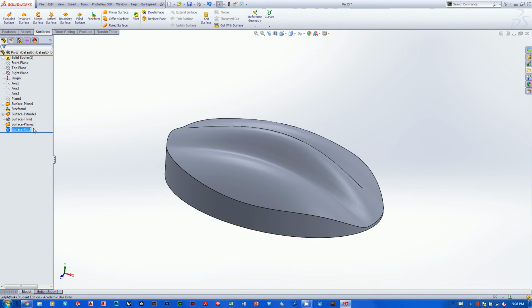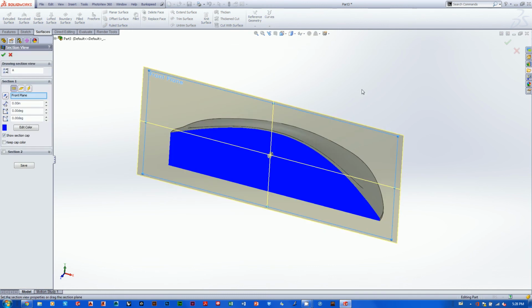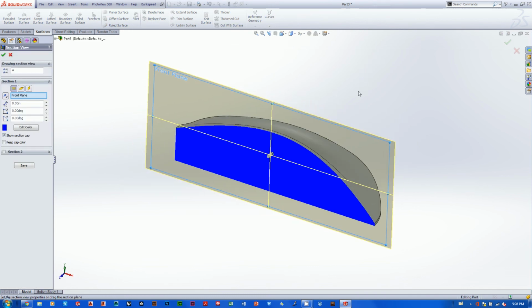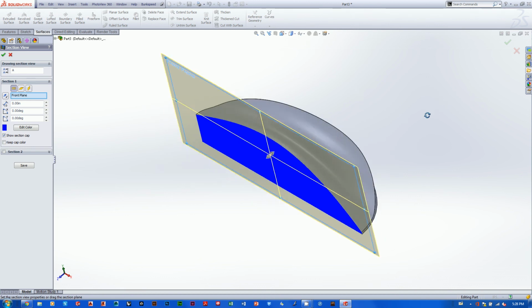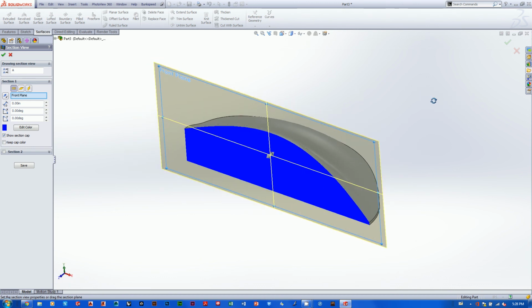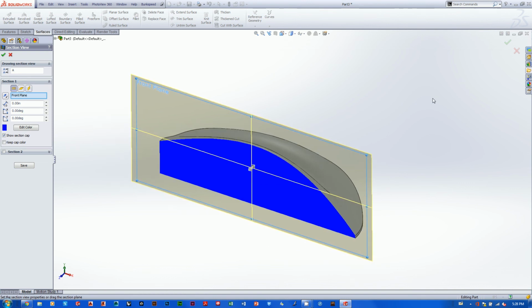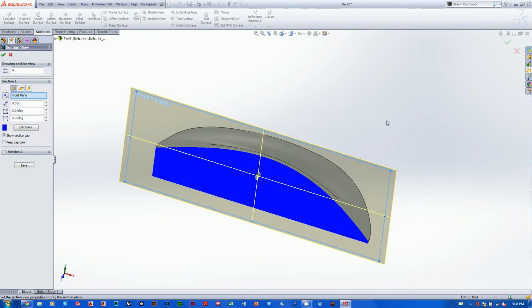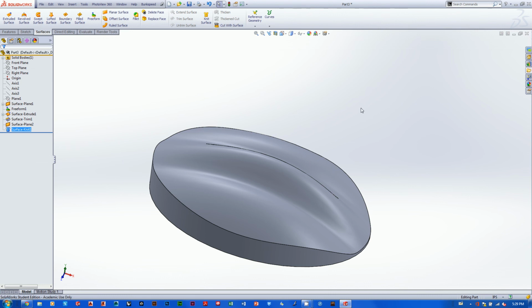Okay, Surface Knit 1 is there. All these surfaces are knitted together. All right, let's check it again. Now what we have is we've created an actual solid from those surfaces. So voila, this is what they call creating a watertight model, knitting your surfaces together. In Alias, they call it stitching a model together. And in Rhino, they call it something else, which you'll find out about in the second section of your class. Okay, anyway, let's exit out of that, and we're going to be happy with this.